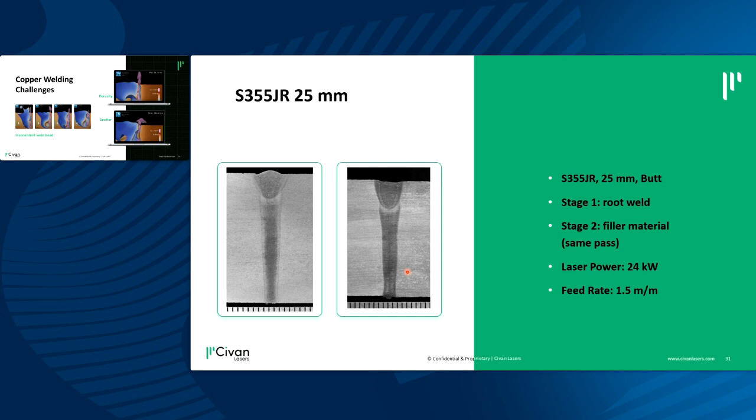Welding of hairpins, I mentioned this earlier. And also when we weld asymmetric copper parts, it could be cables to a thick part of copper or otherwise. By using these different beam shapes, we are able to find the optimal parameters and get a high quality weld.